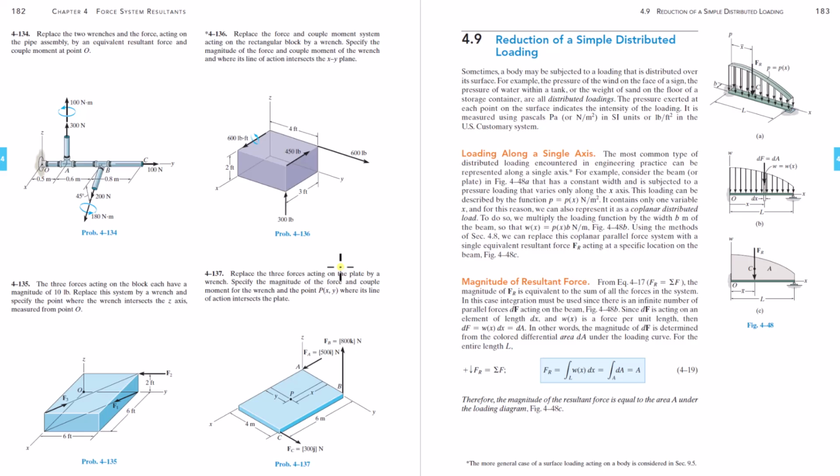One of the idealizations we use is the rigid body idealization. There's no such thing as an actual rigid body. Another idealization we use is the particle assumption. Another one is the concentrated force assumption. That assumption was that if the area of contact of the surface force is small relative to the body you're analyzing, then you can model that force as just a concentrated force at a point and put the force at the center of that area of contact. And that's completely fine. The inaccuracy that results from that assumption is completely negligible.